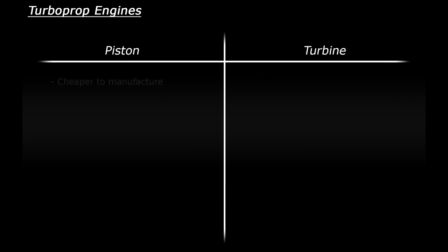Piston engines are usually cheaper because they are relatively simple to design and manufacture compared to a gas turbine engine, i.e. a jet engine. That said, due to the nature of how each engine works, a piston engine does wear out faster than a turbine engine. While turbine engines are more complex in design, they end up having fewer moving parts, so there's less to maintain.